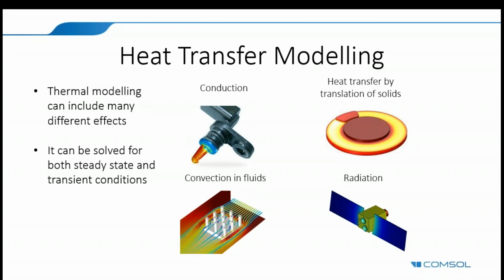The convection, or convective heat transfer, tends to involve looking at particle movement. For example, the movement of fluids, where the convective heat transfer is usually driven by heat being carried by a fluid from an area of one temperature to an area of another temperature. So that will tend to be the dominant form of heat transfer in liquids and gases. Of course, conduction is the case for solids. And this can be modeled as a coupling between CFD and heat transfer.